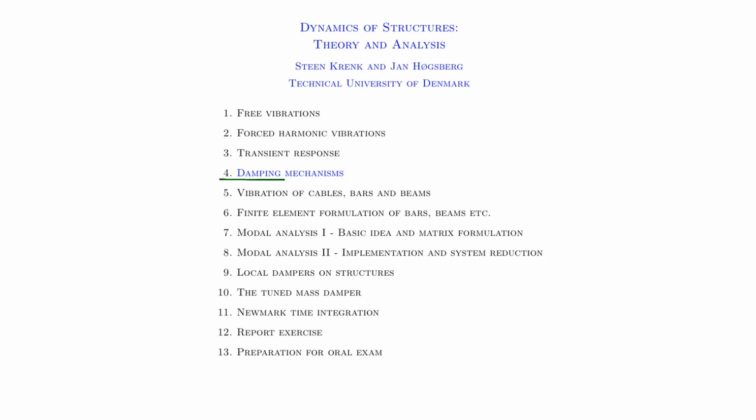So in many real life structures it's actually quite easy and straightforward to calculate the mass. It is also fairly simple to estimate the stiffness either by computer models, analytical solutions, or by measurements where you estimate the frequency. But the damping, that's actually a quite unknown quantity, and in most cases it's actually included in models that are formulated in terms of mathematical convenience rather than to replicate correct damping behavior in structures.